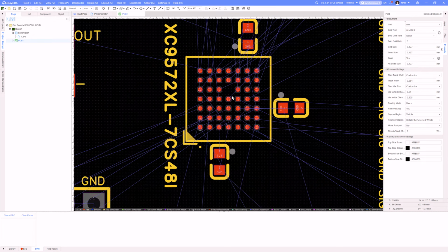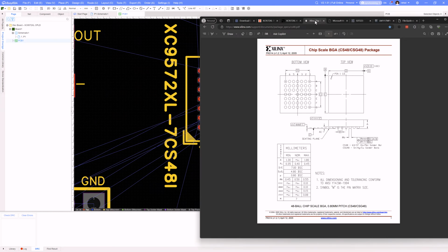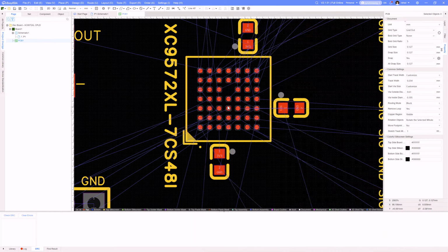This is a BGA, and if I go back and look at the specs of it real quick, or the documentation for it, I'll find this information, but this is going to tell me that the pitch, this little e, the pitch between the BGA balls is a 0.8 millimeter. So not terrible. It's not a 0.5. It's not a 1.0, which I found is quite nice to work with. It's a 0.8. So you got to be careful about how you're going to route through this.